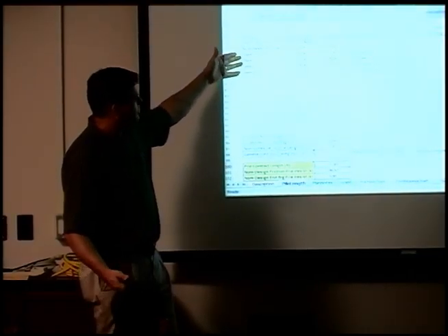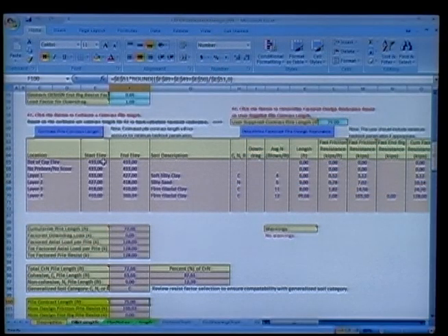But otherwise, we have no scour, we have no pre-bore, so it's going to start with layer 1, and it'll start figuring out the capacities and the lengths in those layers. It'll refeed what you entered for cohesive, non-cohesive. It'll redo the average blow counts. It tells you what the length is, and you can see obviously we're ending in the last layer over here because that's 49.66 feet. You can see the factored friction resistance.